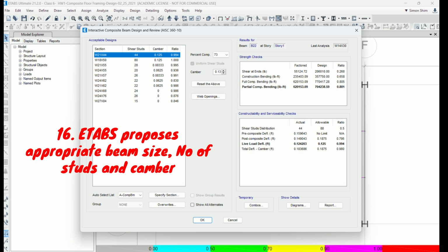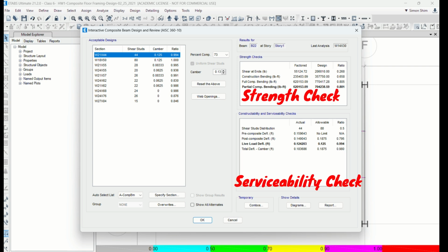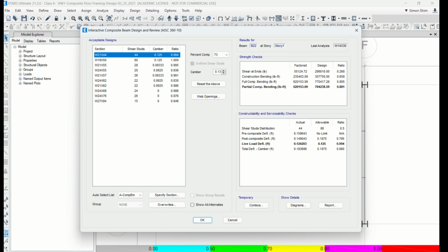Composite beam works between concrete, metal deck slab, and steel, but it has to be tied with shear studs, right? It has to be glued together because it's composite, to get the composite action. With the composite action, this beam works like a T-beam, much stronger and stiffer. We're going to bring some simple models and test it. Or if you have some model wood pieces, a beam glued together with the slab, try to bend it. Or don't glue it, just leave it, press down, and see which one is stiffer. Right? It's physics, just a phenomenon. This is the way it works.